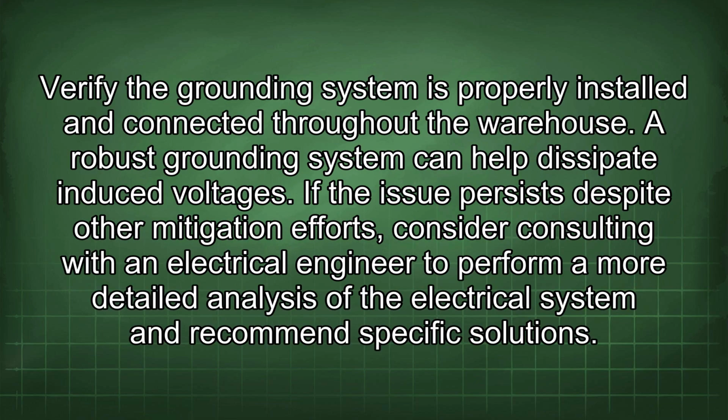Verify the grounding system is properly installed and connected throughout the warehouse. A robust grounding system could help dissipate induced voltages. If the issue persists despite other mitigation efforts, consider consulting with an electrical engineer to perform a more detailed analysis of the electrical system and recommend specific solutions.